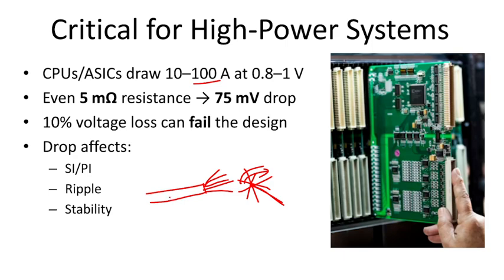But let us say your pipe has some holes here, then water will be leaking out the other side, the pressure will decrease, and this rotating instrument will reduce its speed because the pressure has been reduced. In a similar way, whenever you don't have enough voltage supplied to the IC, even the IC performance will decrease because some amount of voltage drop has happened in your PCB and it is not reaching the IC. So this is one of the simple analogies I want to explain.